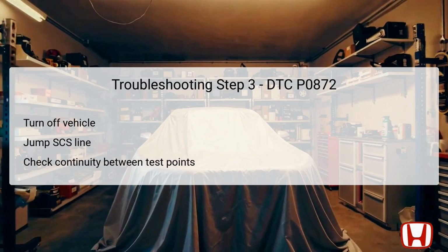With these preparations, you will check for continuity between designated test points to establish whether the OP4SW line has any shorting to body ground. The designated test points involve testing the continuity from the number 26 terminal, blue, of the PCM connector B to a body ground. A successful continuity response indicates a short in the OP4SW wire, which requires immediate repair. However, if there's no continuity, this suggests the wire is in good condition, and the focus should shift toward possibly replacing the PCM to resolve the issue at hand.